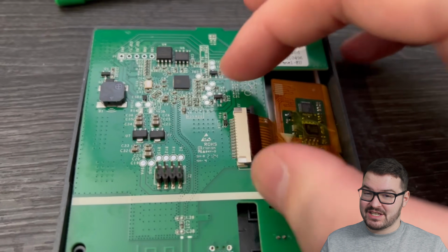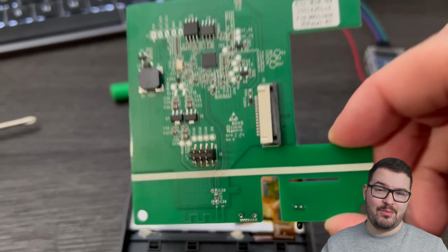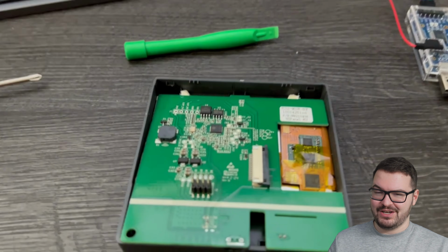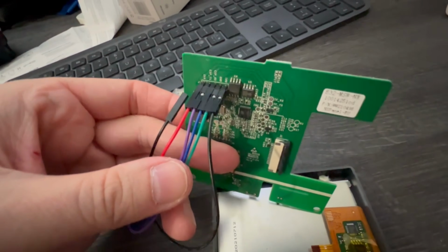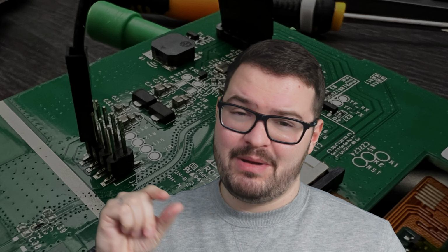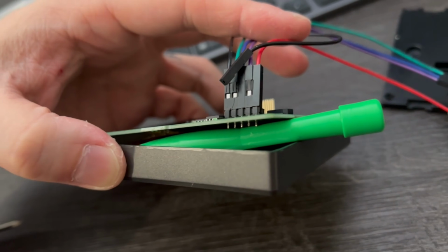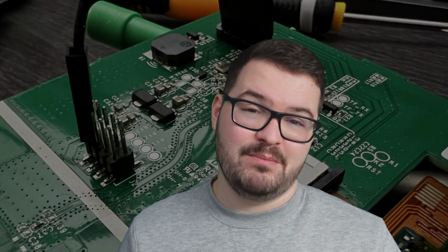The PCB just disconnects from the ribbon cable and then you can flash the PCB by itself and then put it all back together. I personally choose to not do this just because it saves me having to undo things and put lots of things back together, but that's just me. If you're also copying along and you find that your pins are too long, if they do stick through the board fully, then they'll actually touch the metal plate beneath it and they'll short out, and that will stop the panel going into boot mode.